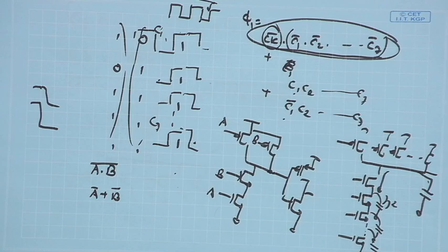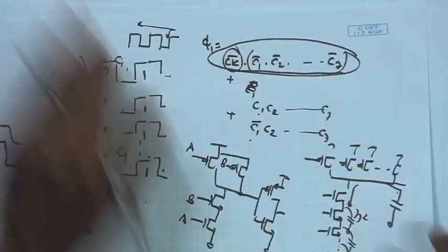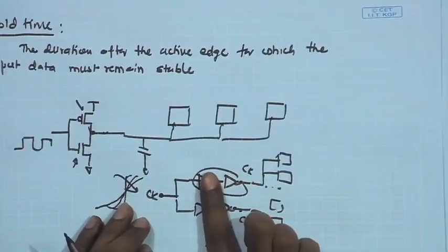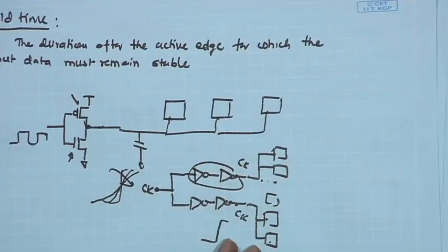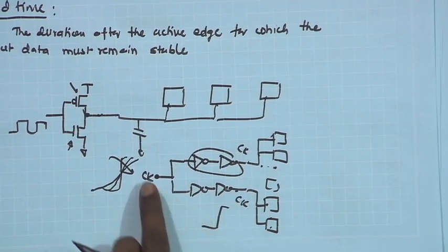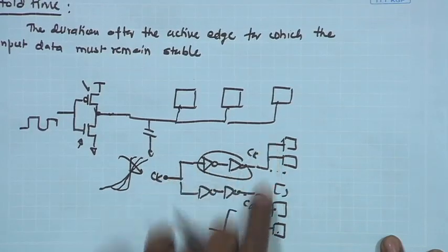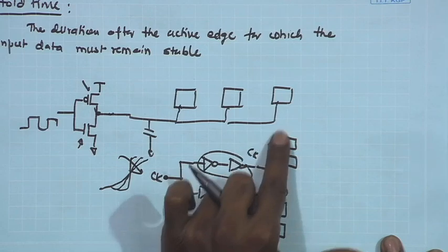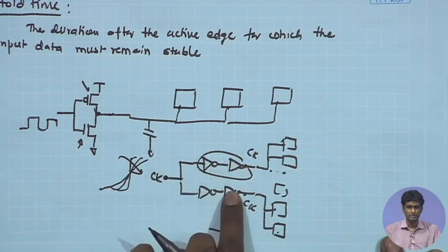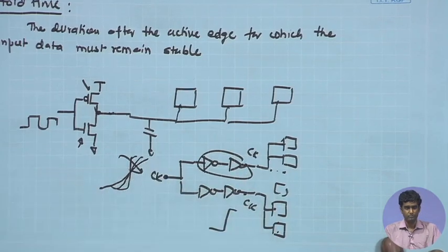So, in case of bifurcation, you added 2 inverter buffers. Why can't we simply divide it into 2 parts without adding the buffer? If you do not add the buffer, then the load capacitance remains the same. That is the main purpose, right? Dividing the load capacitance and making it smaller. So, if this was connected to 8 logic gates, then the fan out of this was 8. Now, I inserted some buffers, and this buffer is driving 4, this buffer is driving 4. So, the fan out of each of these is 4.